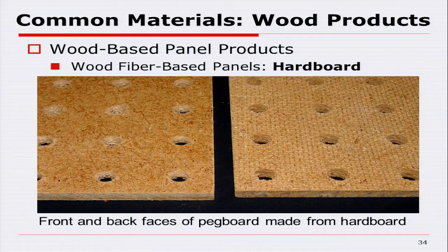It's a smooth plate on the other side, but it has to have a screen on this side to let out that steam during the pressing process. They'll come back and put this through a press again to get both sides smooth. That's just an extra operation. If you're making pegboard, they don't go through that extra operation, so on pegboard you typically see that screen print on the back. That's just the manufacturing process.